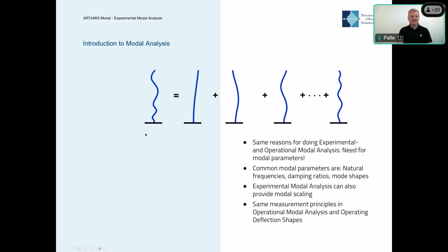So you could imagine this is in the physical domain, that something has caused this to vibrate. And modal analysis is simply, you could say, a mathematical way of getting the modes of vibration that, you could say, give us this sophisticated vibration in some very simple ways. We get a mode shape, and we get a natural frequency and a damping ratio. In case of experimental modal analysis, we also get something we call the scaling factor. But these are the modal parameters.